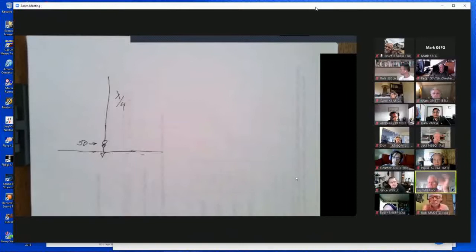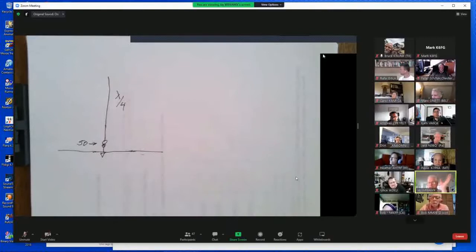Well, the wire is shielding it from itself. The inner side of the wire, right at the center, doesn't even know that anything's going on on the outside, because it's got a lot of copper between it and the surface. Most of the current flows along the surface, which is why, first of all, you can use tubing as a good antenna, but you will get some losses here.